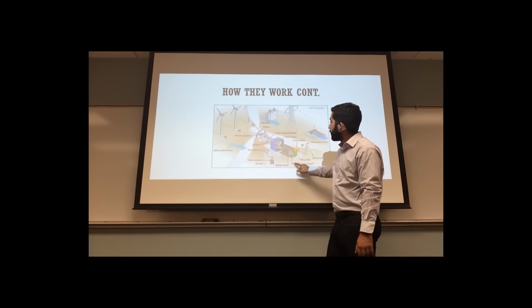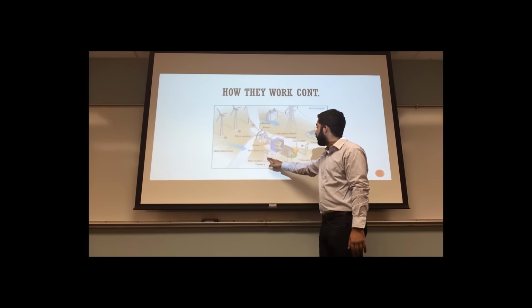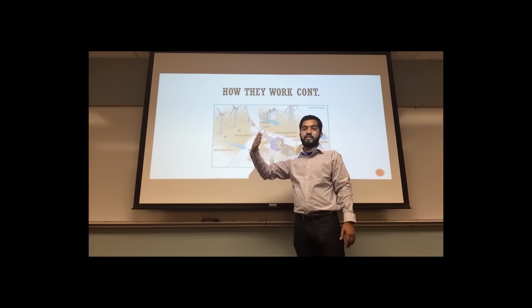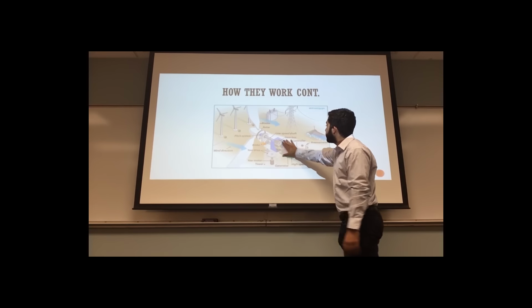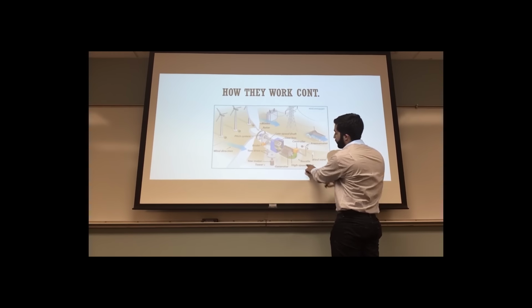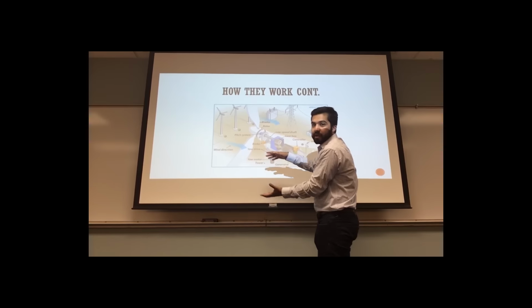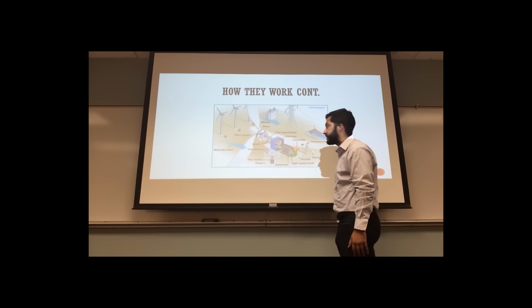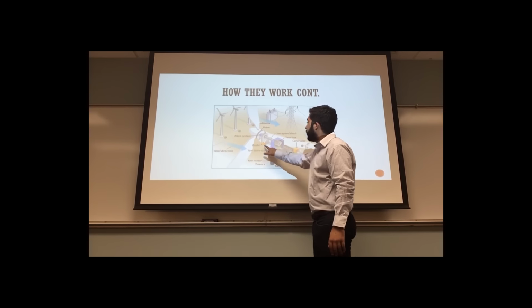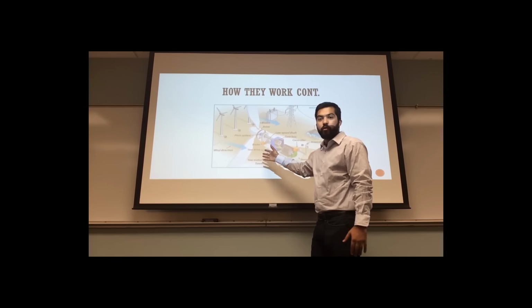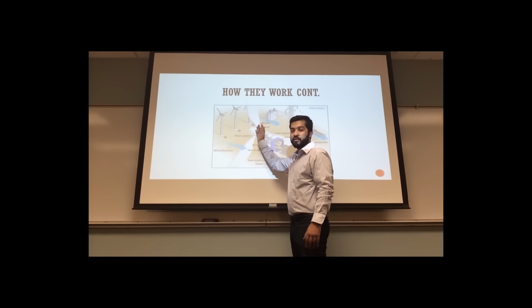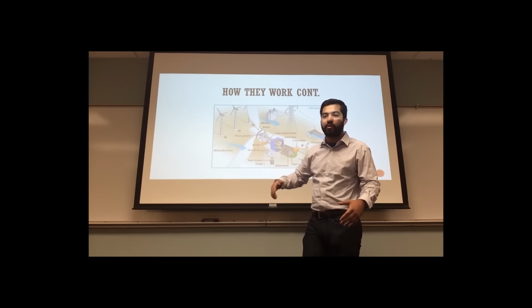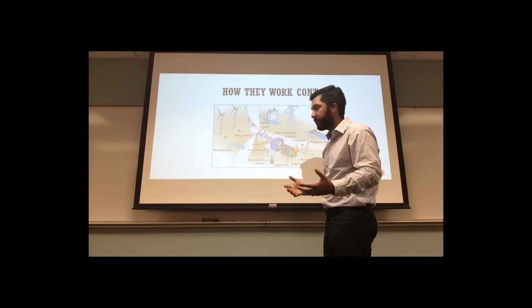The controller then sends power to the yaw drive and the yaw motor, and it will actually turn the entire assembly. All of these things are housed in a nacelle. The nacelle, as it's stated here, is just like one big aerodynamic duct that covers, like your hood or an engine nacelle in an airplane. We also have a brake. When you're performing maintenance, you want this thing to be stopped. So we have a brake. It can be a mechanical brake, it can be an electrical brake, it can have many different types.